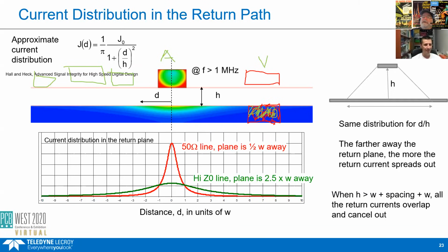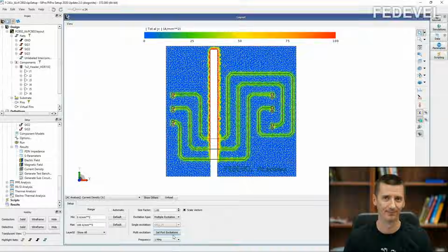That's why you want to do everything you can to avoid gaps in the return path. And that's why when you watch the other guys show how to route traces on a board, and they route all their traces first, and they use the top and the bottom layer to route the traces, and then they throw copper pour, and they say, okay, this is now my ground connection, we'll connect to the ground net. That's worse than you can possibly do, because you have automatically engineered ground bounce in your design. Worse than you can do.